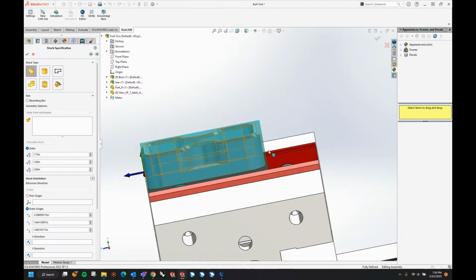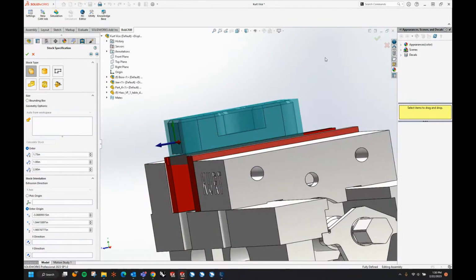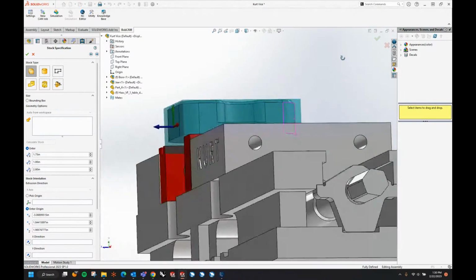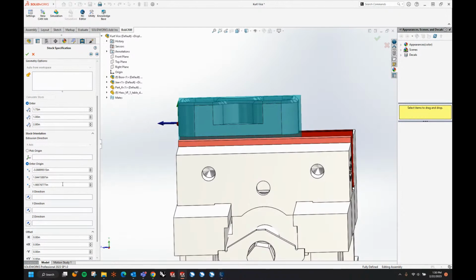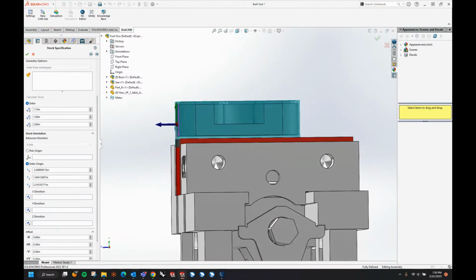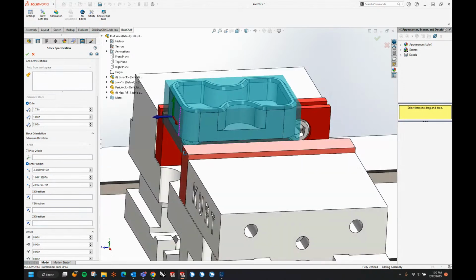You'll notice that it only added to the one end. And it's really easy for this to happen in SolidWorks because you're kind of free to draw wherever you want, where Z might not show coming off the part correctly for the stock definition. So I'm just going to go over to my Z, and we're going to add 25 thou. That should have shifted it down to the middle, which it is.